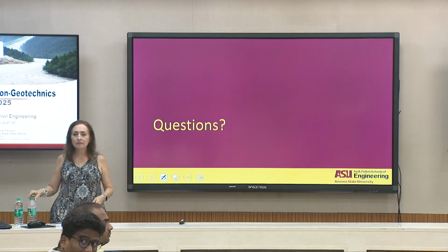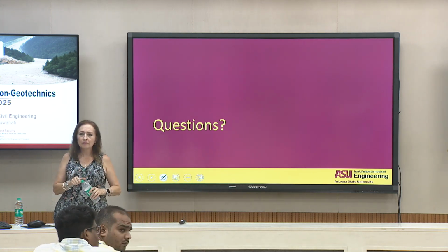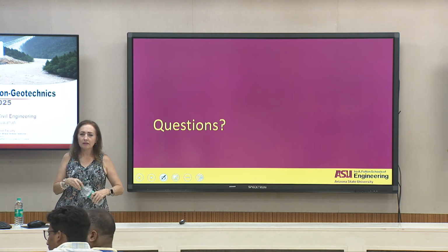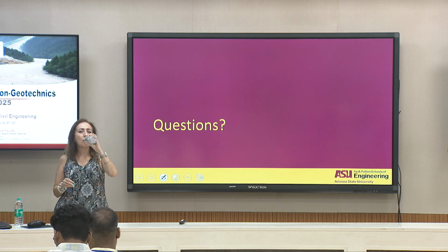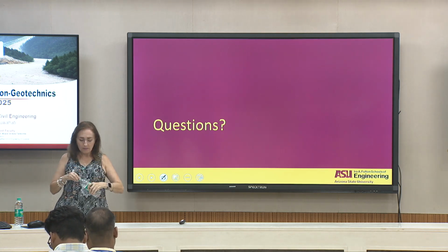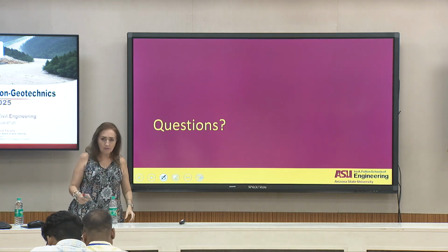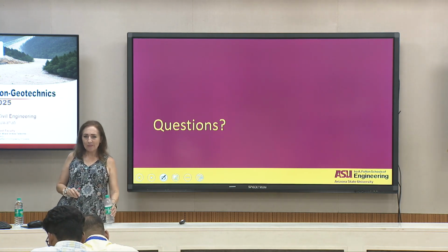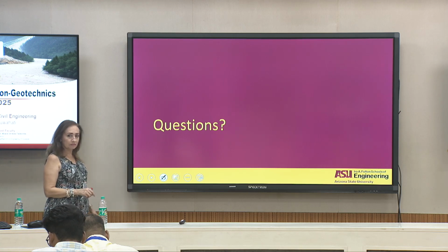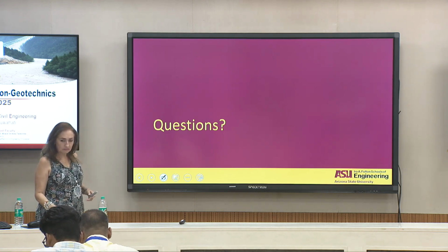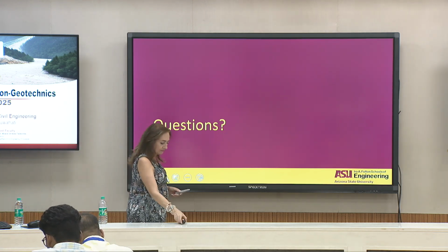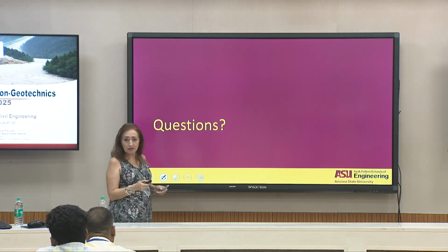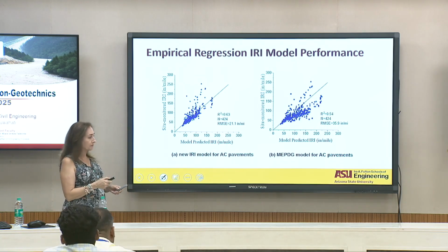When field deformation measurements were done for volume change, parallelly there would be traffic going on, right? So based on the age of the pavement, it would be either in the primary or the secondary compaction stage. So the data is coupled with both traffic movement and the soil character. And you're talking about the data we use for the calibration?